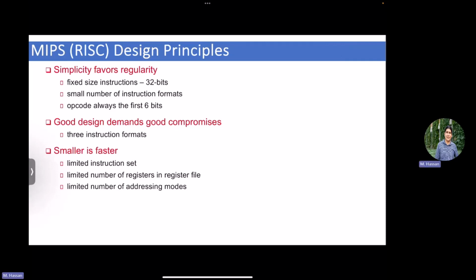Again, when we say limited compared to the CISC, where any instruction can in fact have a memory direct address to perform the operation on, right? We never mentioned here that part of your operand is in fact a direct memory location, other than for the load and the store, right? But if we talk about the example we gave earlier about x86, an add instruction can have all 3 operands as memory addresses.